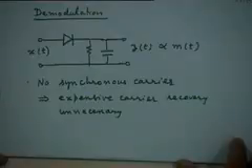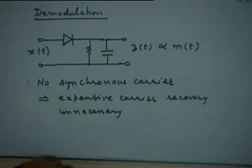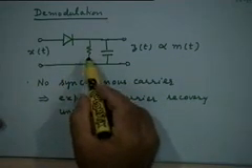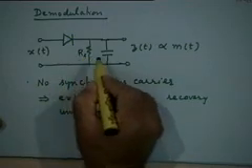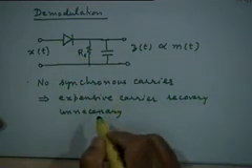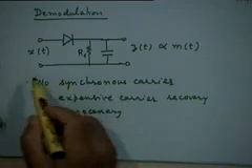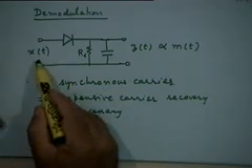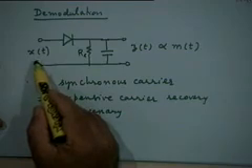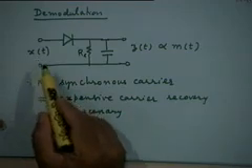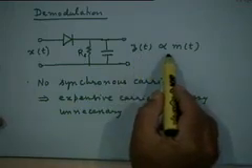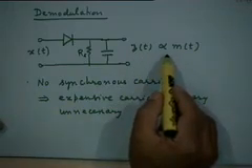We will discuss it in more detail now, where you have a simple diode followed by a resistor R sub L in parallel with a capacitor C. And our premise is that if at the input you apply the amplitude modulated signal x of t, the output z of t will be proportional to the message waveform m of t.